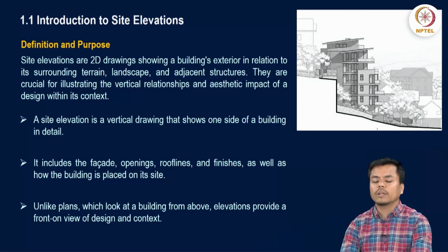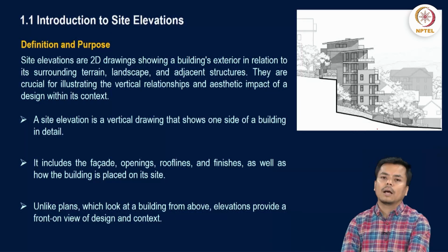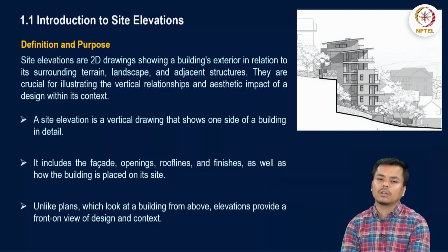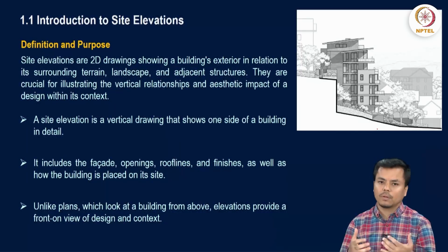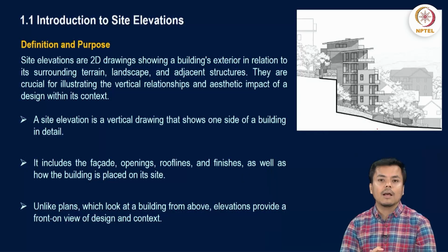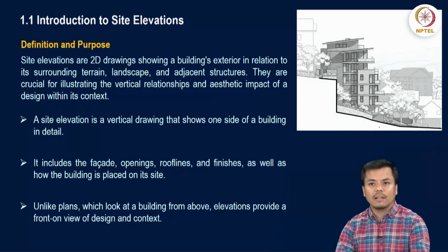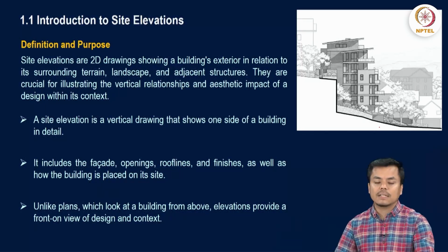To explain why site elevation is necessary, you may have this question: you have already showcased the elevation of the structure, so why is there a need for site elevation? You may think that there is nothing that can be displayed from site elevation, but that is not true in reality. Site elevation is a 2D drawing, the same as an elevation, but it showcases the building's exterior in relation to its surrounding terrain.